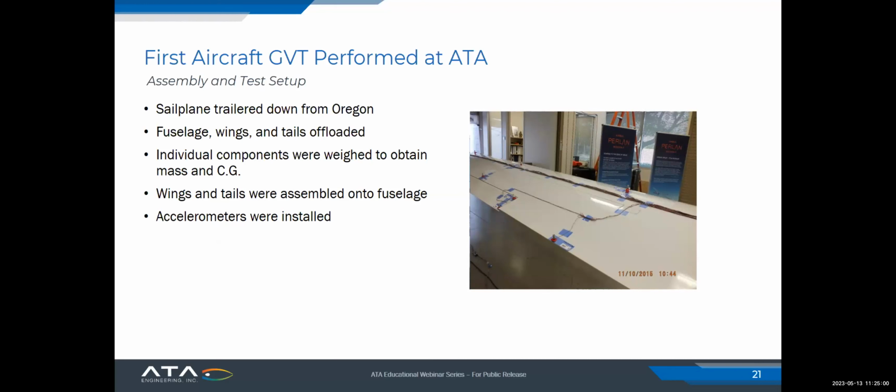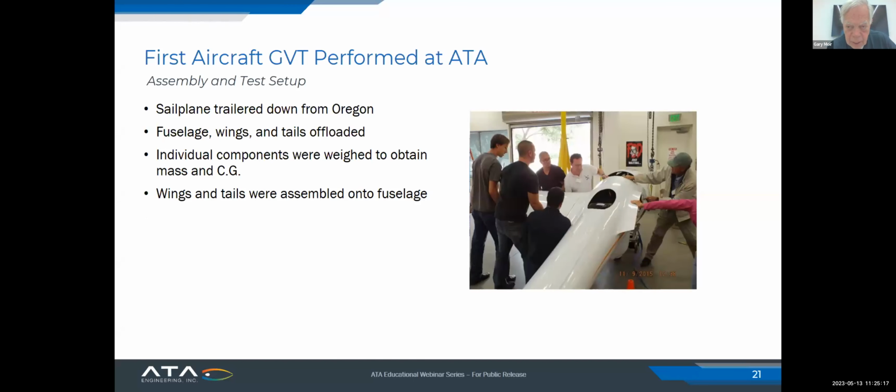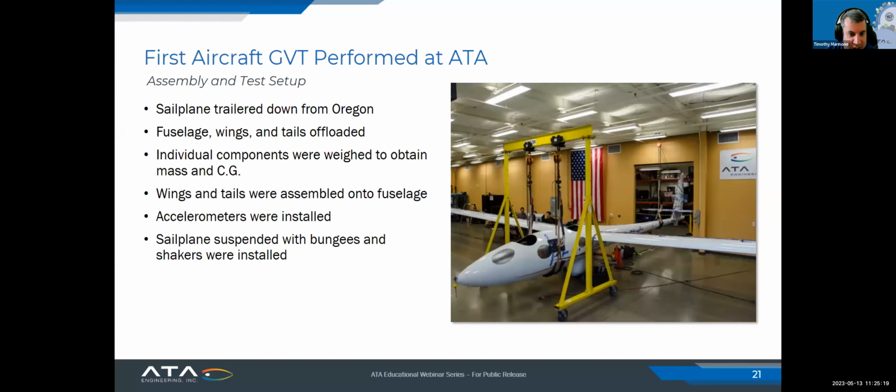Okay, all right, that's it. Thank you. Of course, the mass moments of inertia are very important in flutter analysis, particularly on a long, thin wing like this. I'm curious about what the aspect ratio is, but did you attempt to significantly change the mass moments of inertia by putting any ballast weights at particular locations?